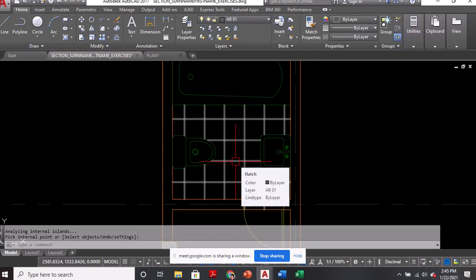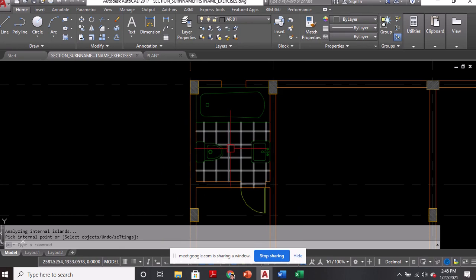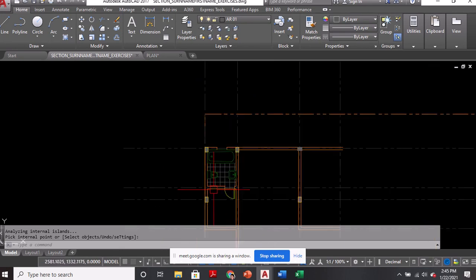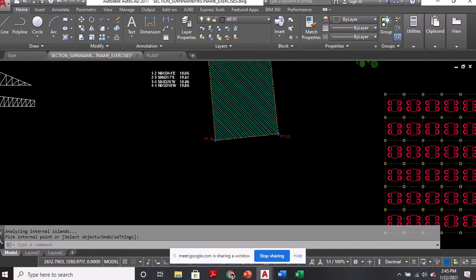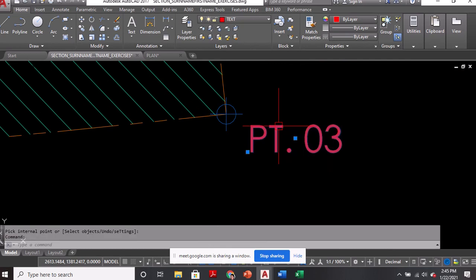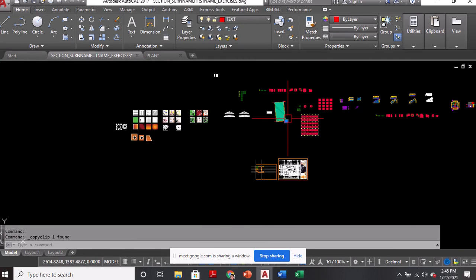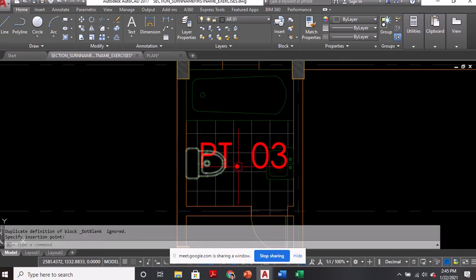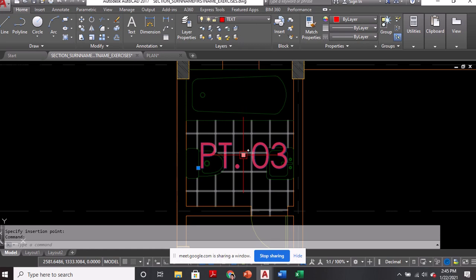So, after that, we have to label this room. Okay? So, we use text objects for labeling our rooms in AutoCAD. So, meron tayo dito at ito yan. Okay? So, you can create the text ulit or you can just simply select this one, Control C to copy, and you paste here, Control V. Now, you select this one. Remember when you label rooms in CAD, in architectural drafting, you do it sa bandang gitna po ng room. Okay? So, you click that part.